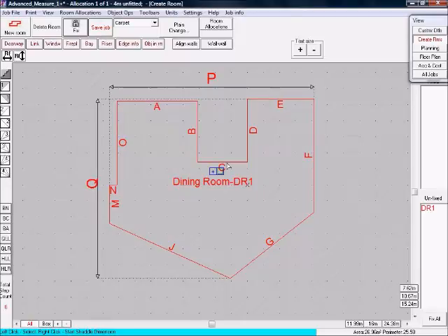You right-click with your right-hand mouse button on the corner of these walls. You will see that your cursor gets a circle. Now click on Wall to Wall, and then do a normal left click with the mouse on wall C. You are given a straddle arrow, so enter its measurement as 3.5 meters.